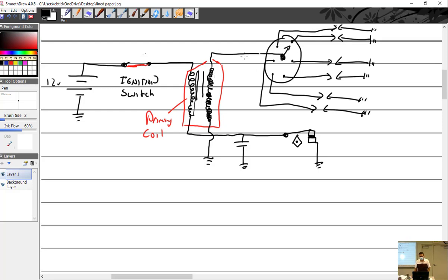But we have all this voltage that goes, we'll jump a very small gap right here, go to the spark tube, the spark plug. And remember, we must have a complete path all the way around. So where's my path? In the ground, it's got to go from the ground to the ground of the second coil, to right there. There is a complete path.